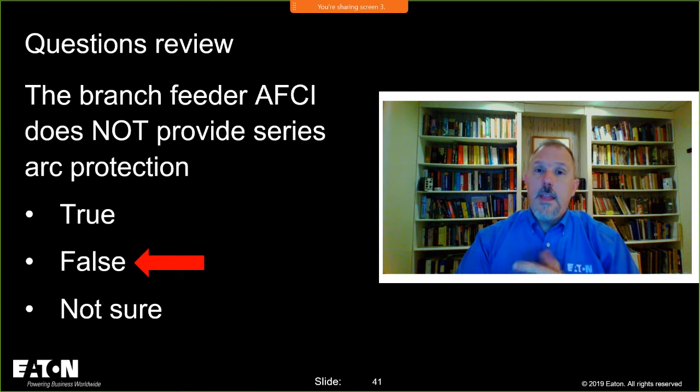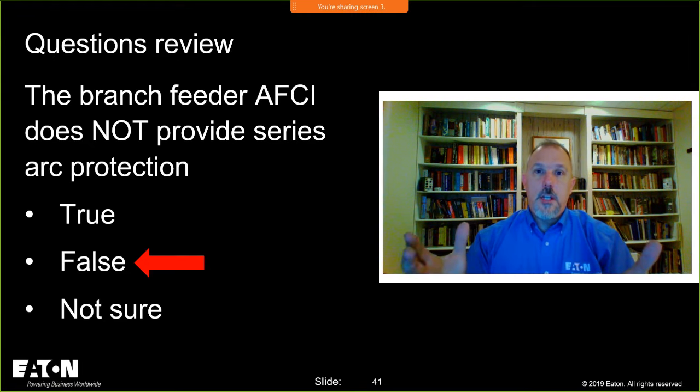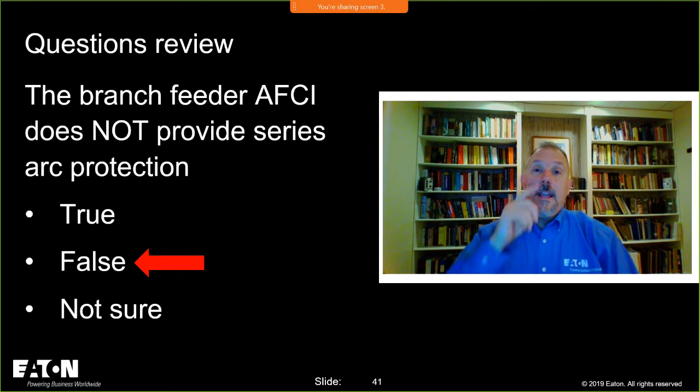Now, when they removed that, you removed the deterrent from slapping two devices together, because GFPE is what would make it so that you can't share a neutral with two devices and put a handle tie on it. So now you think, okay, I don't have ground fault in there, and I'm going to slap these two devices together instead of buying a two-pole, and put a handle tie. Well, here's the issue with that.